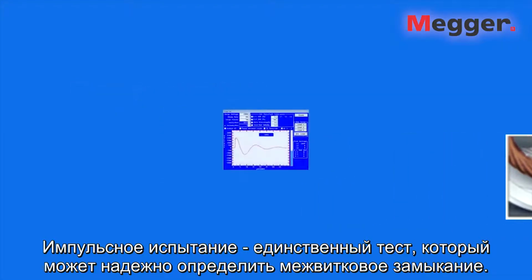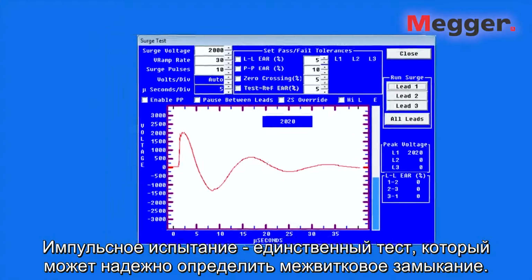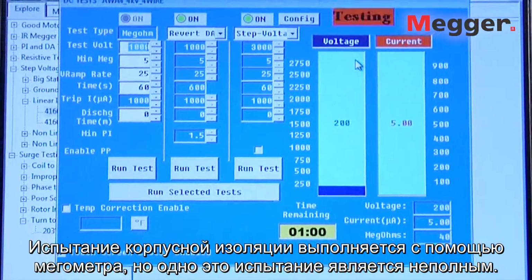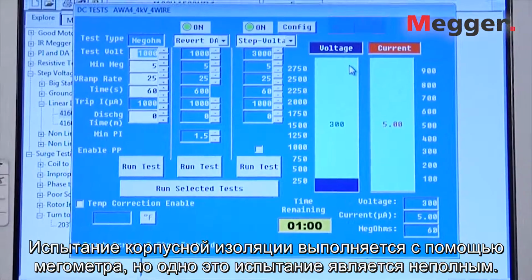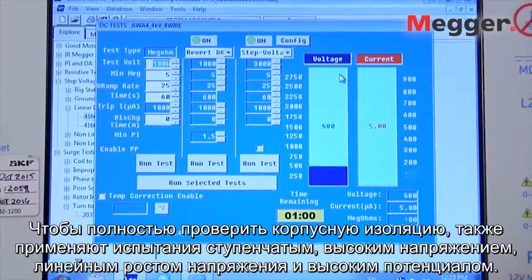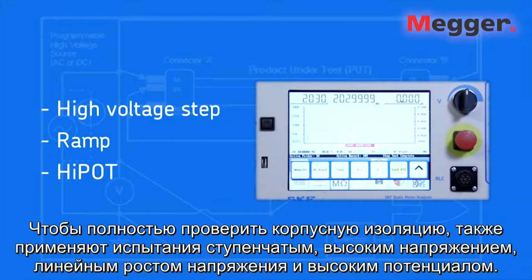The surge test is the only test that can reliably test turn-to-turn insulation. The surge test also finds phase-to-phase and coil-to-coil faults in the stator windings. Ground wall testing is done with a Meg-Ohm test, but Meg-Ohm test alone is an incomplete test of ground wall insulation. To completely test the ground wall insulation, high voltage step, ramp, and high pot tests are also used.